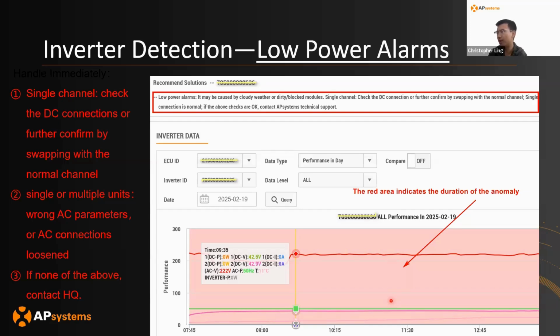What I generally recommend installers do is, at the beginning of the day, just turn on the ECU connected to the internet, and have the microinverters synced into the ECU. Then as the day goes on, as I install the microinverters onto the roof, the ECU will begin to link up with the microinverters as they build up.